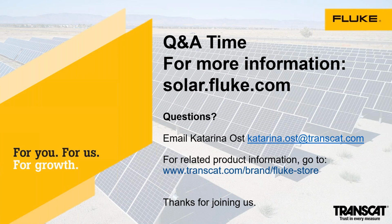If you're doing module level testing, where you're only testing one module, which we see people do a lot when they're doing module degradation testing, that's fine. Most modules have a voltage rating somewhere around 40 or 50 volts, much below the 1000 volt rating of the SMFT. If you're testing a 1500 volt string, what you can do is split the string in half. So you're reducing that voltage and getting it below that 1000 volt threshold. That is a way to use the SMFT 1000 on a 1500 volt string.